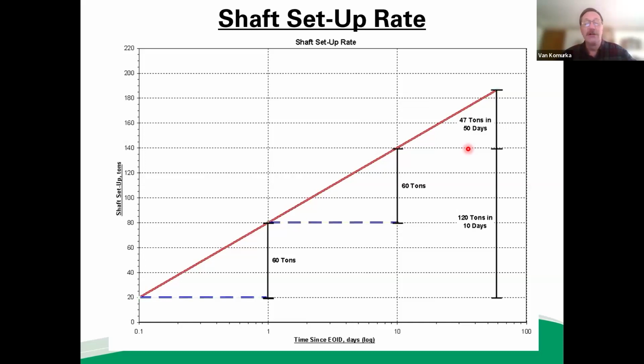We always get asked, how long should we wait to restrike, to characterize setup? And it depends on a lot of things, mostly site constraints and schedule. I always tell clients, the longer you wait, the more setup you get, but waiting too long isn't worth it.